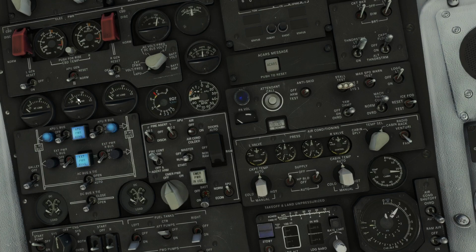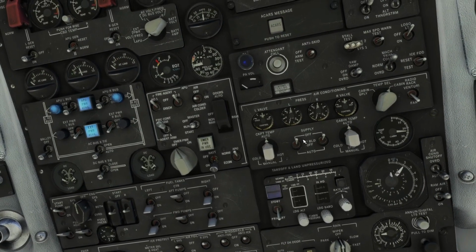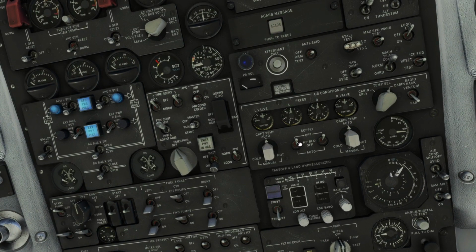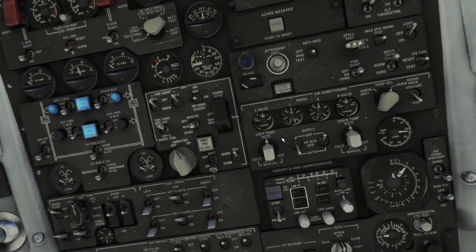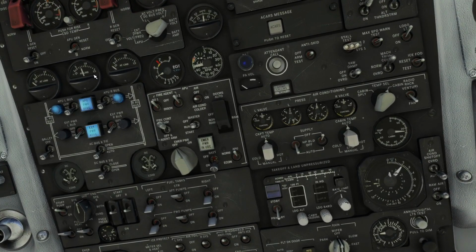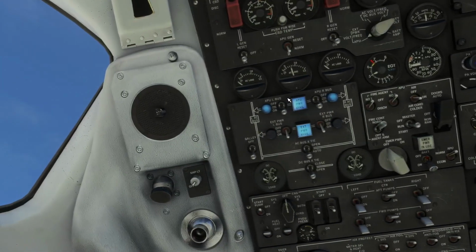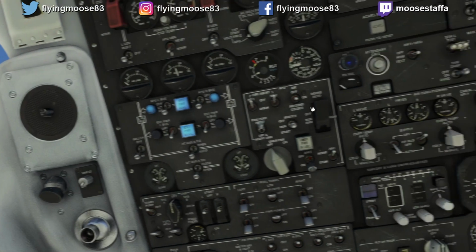So we're showing right about 70% of load, and I'm going to flip on the first pack right there. And I don't know why it moved my view when I did that. It wasn't supposed to do that. There we go. But you notice that thing jumped a little bit. This indicates a pressure amount, a PSI in the duct for the pack, and you could probably also hear the air conditioning sound changed a little bit. You actually have stuff blowing. And you can see now we're getting a little closer to 80% load on the APU.